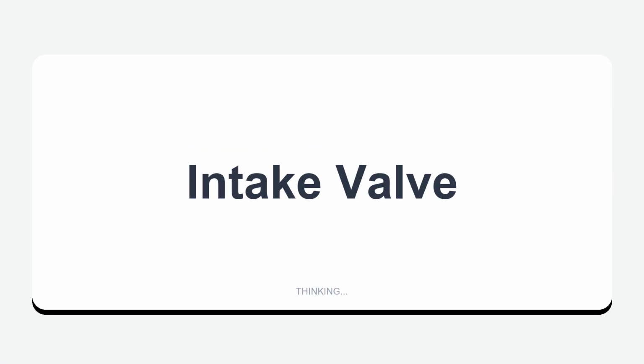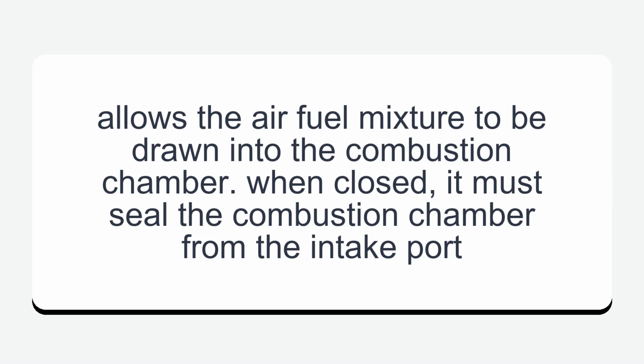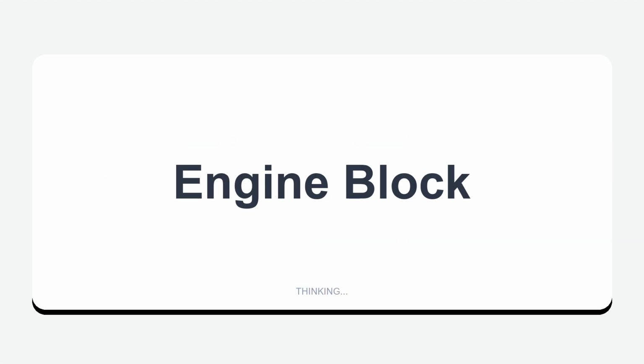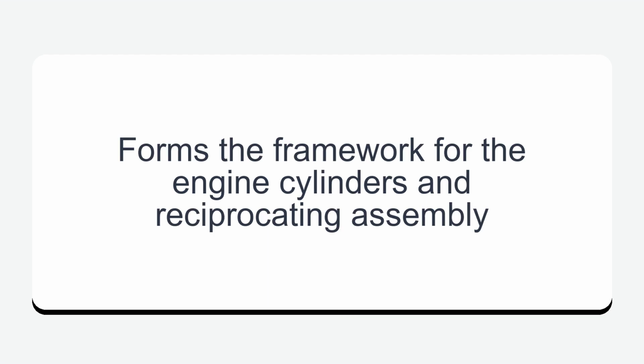Intake valve. Allows the air-fuel mixture to be drawn into the combustion chamber. When closed, it must seal the combustion chamber from the intake port. Engine block. Forms the framework for the engine cylinders and reciprocating assembly.